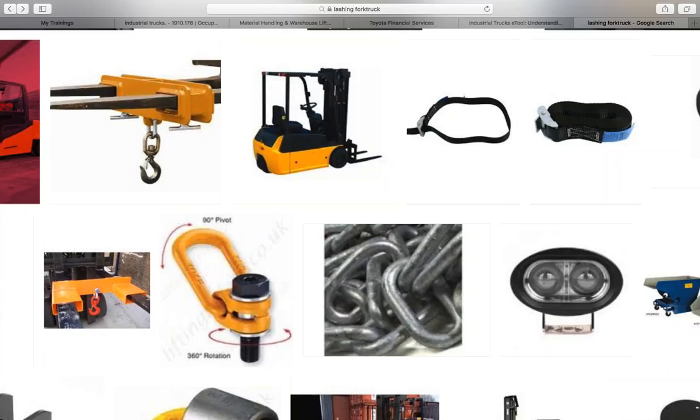And the way you know that is because if you notice that the boom is attached to the rear of the structure of the vehicle, so that's why it's a SkyTrack or that type of equipment. Okay. And you see how that center of gravity keeps moving, right? Depending where the weight is, how it's distributed, and that's what the risk is. So the higher we go, if you notice what we're doing, is the higher we're pulling that center of gravity. Okay.